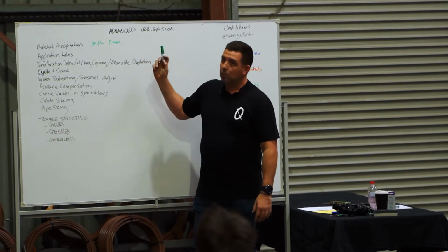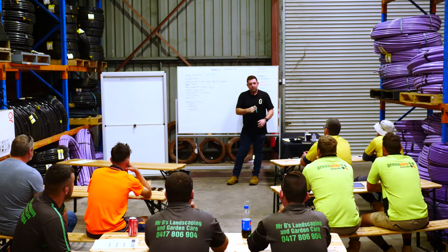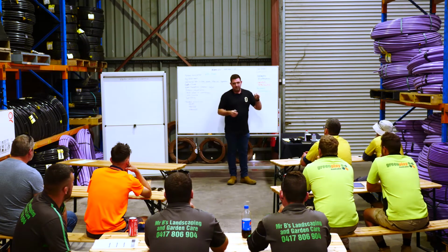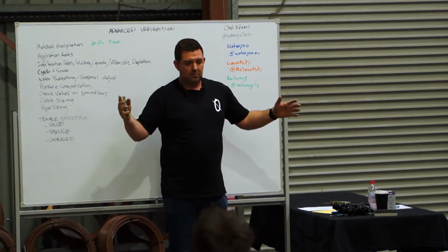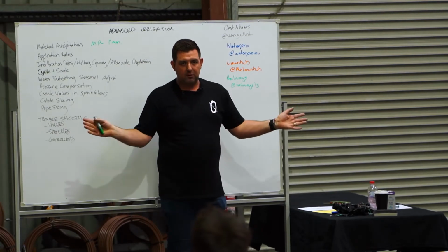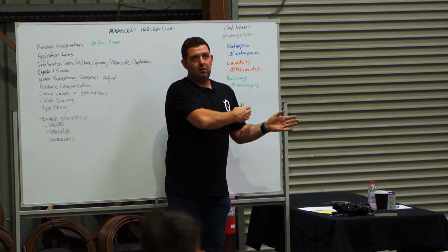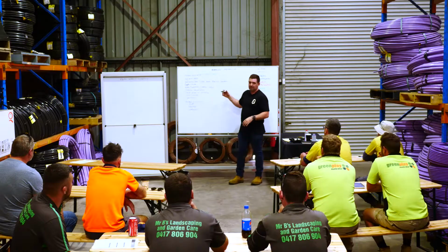situation. When we design, say, an open space like a large oval, if we're using a sprinkler nozzle in a standard gear drive and the nozzles are 3 gallon per hour, we'll then put a 1.5 gallon per hour nozzle in the quarter. So we'll have full circles at 3, and then we'll do half circles at 1.5, because obviously a sprinkler is going back and forth twice as often as a full circle. So then we have to allow for that to make sure that we're getting matched precipitation.